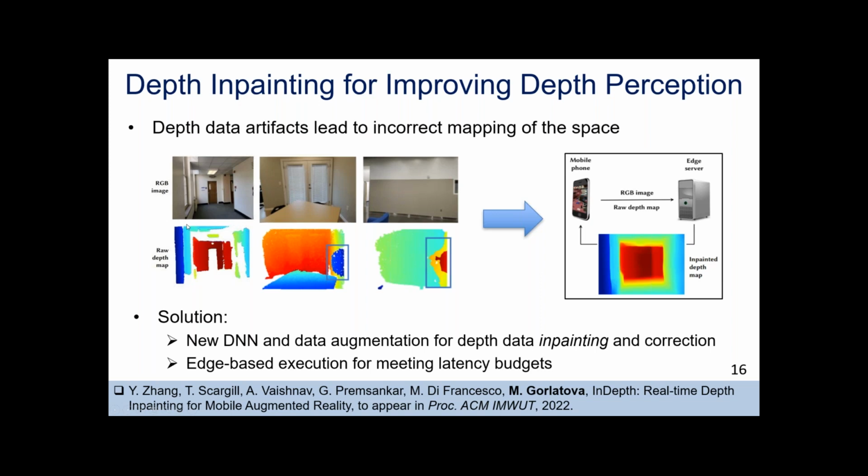So for a very large number of pixels, the depth just isn't recorded. And this is a very common occurrence. We have seen this on headsets and mobile phones both. And it has to do with the properties of the type of sensing that's done to obtain depth data. The sensor generates infrared light that's sent into the environment, and it receives this data back. But how well the received data looks depends on the surface that was encountered by the infrared beam.